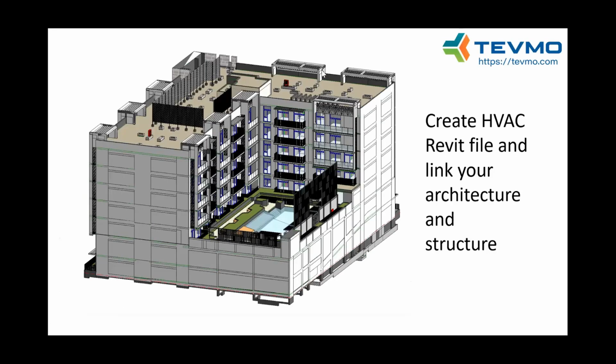So first of all, we only consider the situation when you have a BIM file in Revit. What we are talking about today is calculating cooling loads in Revit. The first thing you need is architecture and structure in Revit. Then you create an HVAC Revit file and link your architecture and structure. If your engineers work in Revit, then you probably know this part, and you always link the architectural file.